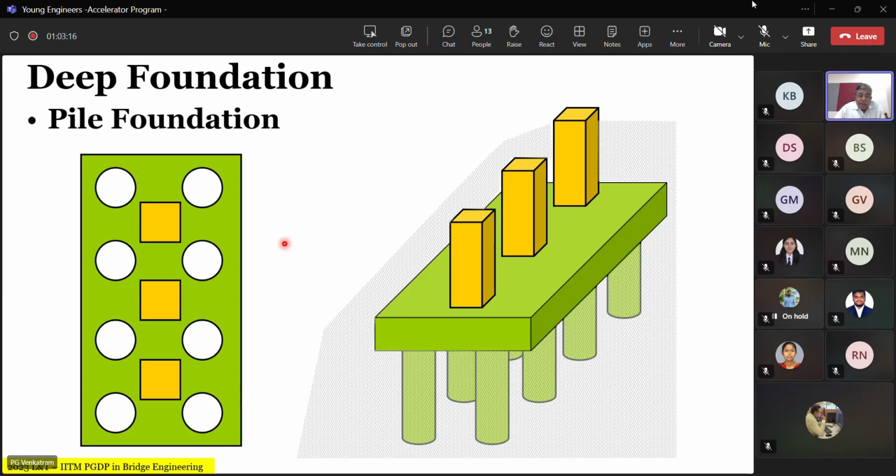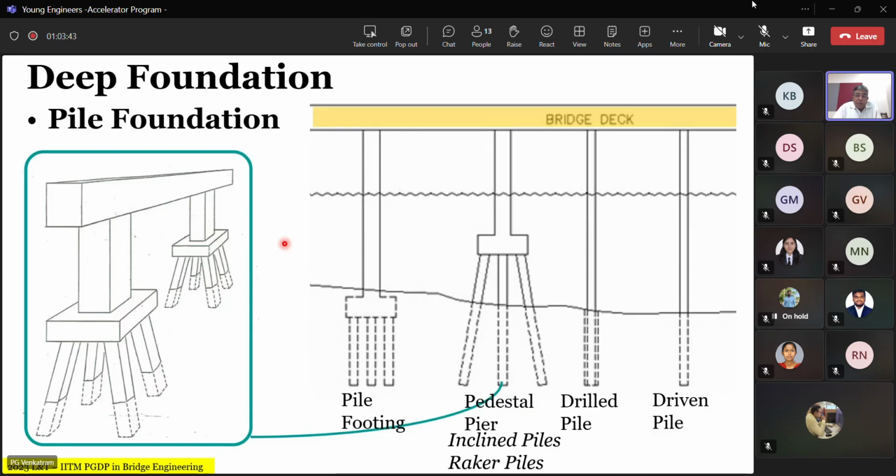Most of the very deep foundations have been pile foundations. I don't know if you have been following, there is a bridge being constructed in Maldives by an Indian company called Afcons. They have installed a pile which is around 230 meters long in about 130 meters of standing water in the sea. So bored cast in situ foundations can be done to very large depths, right? So in the pile foundations, you have again many choices.